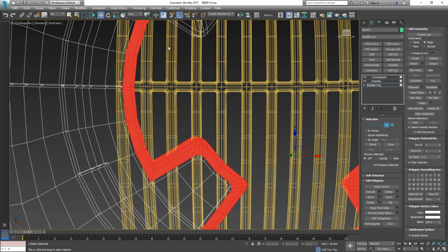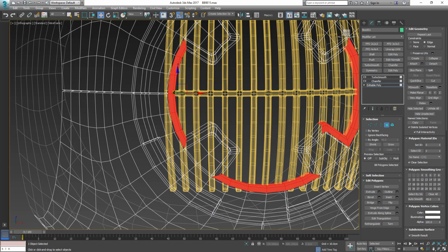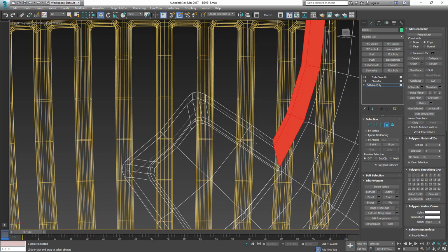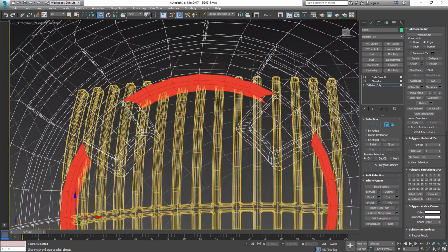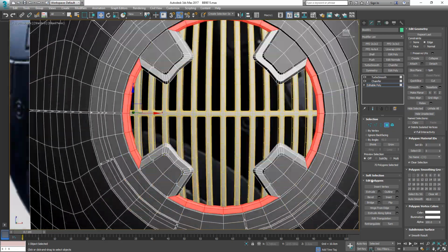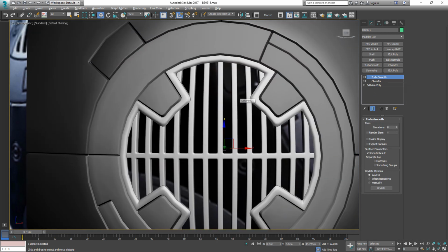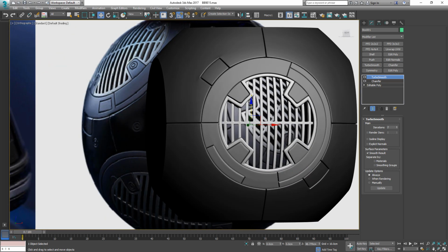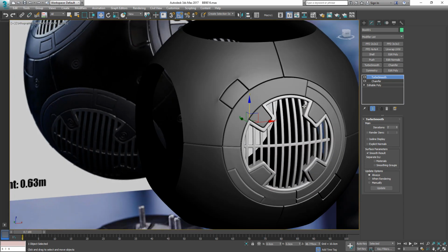If you want to know more about this technique here, you can watch my high poly special on YouTube where I explain that more in depth. But for now, all that we need to know is that we need to have different smoothing groups here. Once we have this selection, we're gonna assign to it. Make sure we have them all and then click auto smooth once again. And that tells our chamfer modifier, which we now have back on here with the turbo smooth, that this is where it needs to make some nice divisions so that it actually does the job.